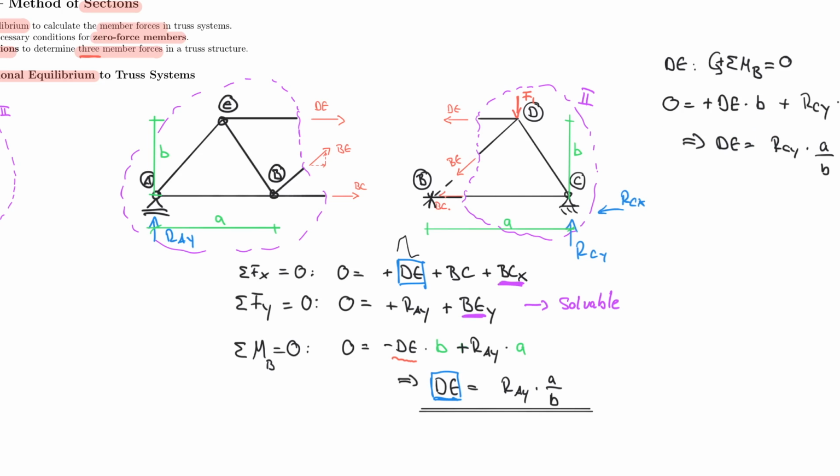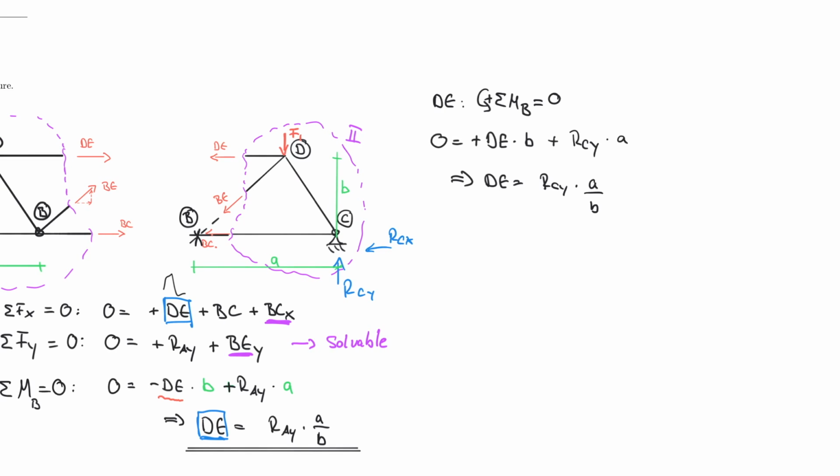So I would have to add this to my equation, and I'm going to do that for you just for good measure, to have all the possibilities covered. So let's see where we would add that. We would have F1, and that would now be multiplied by A over 2, because we assume that node D is exactly halfway between node B and C. That's not very precisely drawn here, but that's usually how those structures are geometrically arranged. So F1 would be right at this point, turning about this point, so A halves.